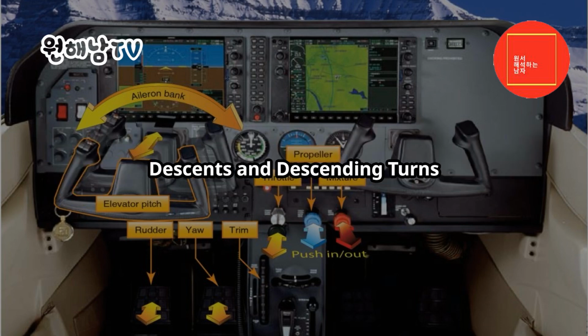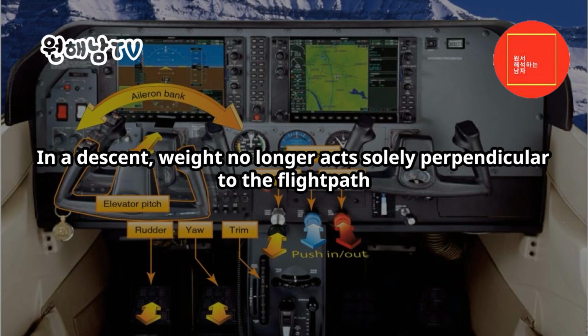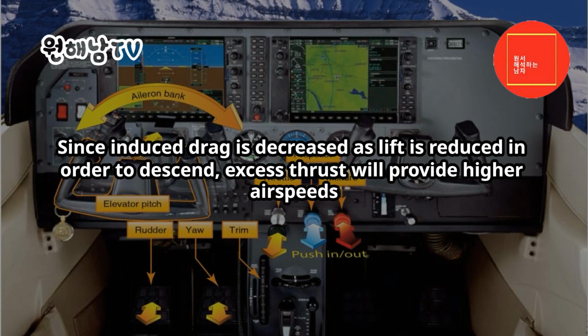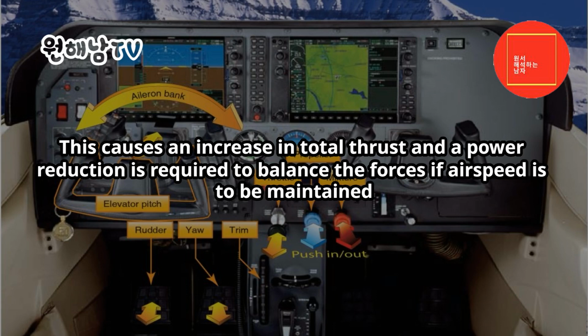Descents and descending turns. When an airplane enters a descent, its attitude changes from level flight to flight with a descent profile. In a descent, weight no longer acts solely perpendicular to the flight path. Since induced drag is decreased as lift is reduced in order to descend, excess thrust will provide higher airspeeds.